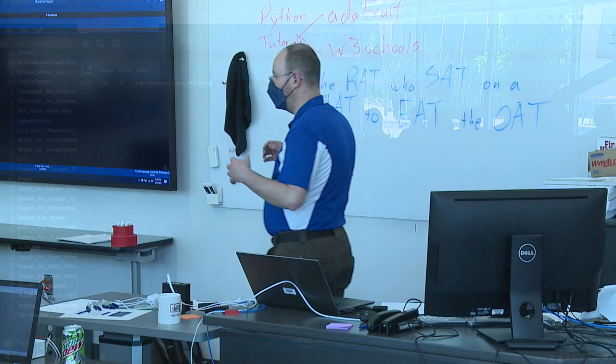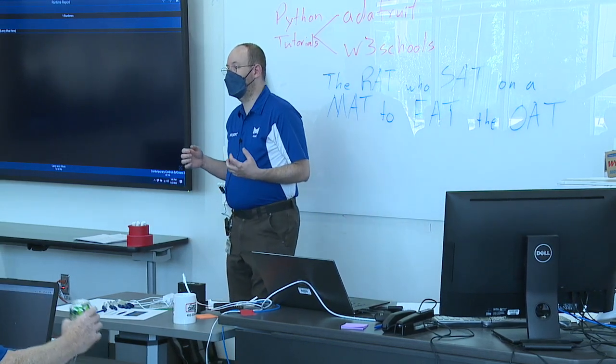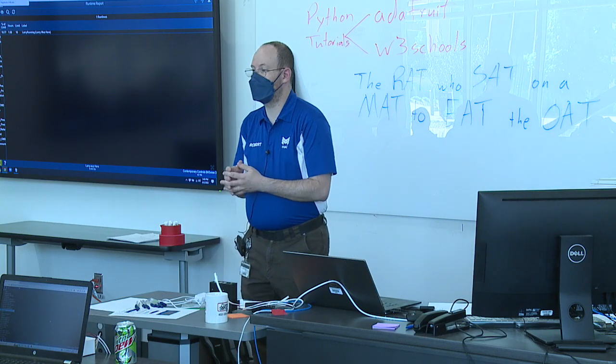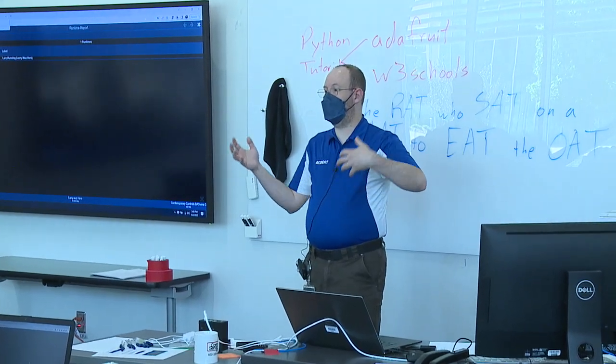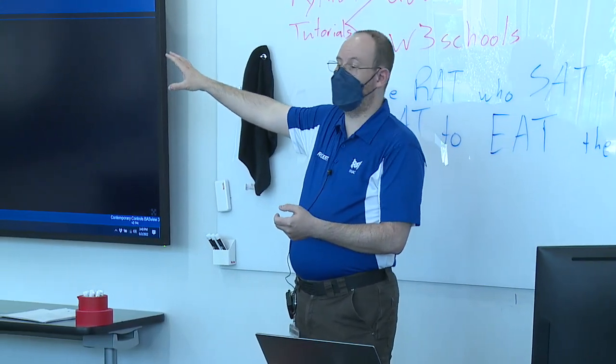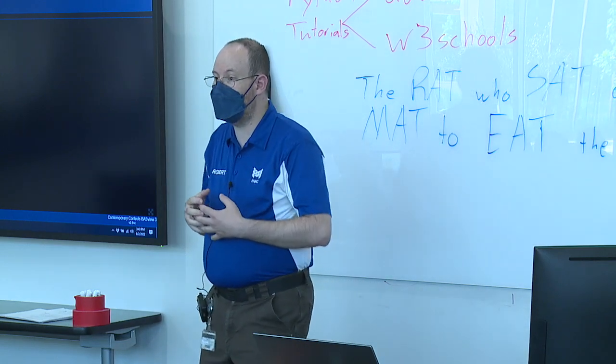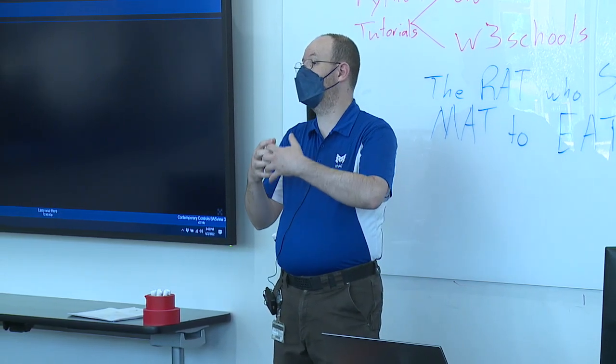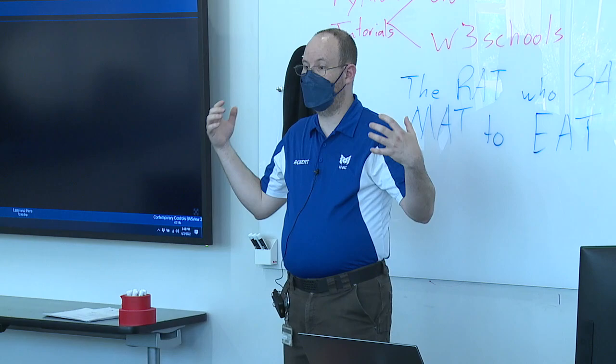That's fine. So, when we start talking about graphics, from an operator's standpoint, depending on your operator, don't throw books at me, it's about 90% of where the rubber meets the road as far as the building control system goes. Most operators live and die by the graphics. You will run into some operators who hate the graphics, don't believe them in the first place, so don't use them at all. You will run into an occasional building operator who used to be a controls technician who doesn't like the graphics because they don't give enough information, and so they dig into the back end to get the information they want. But the vast majority of the time, the graphics are their touch point.